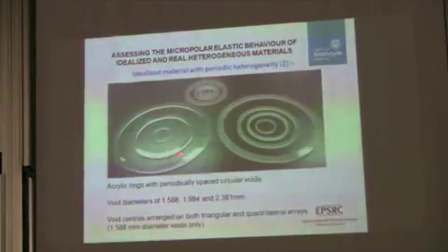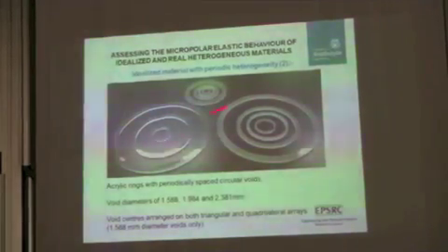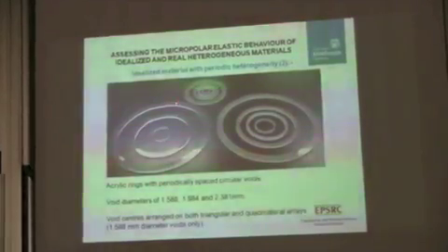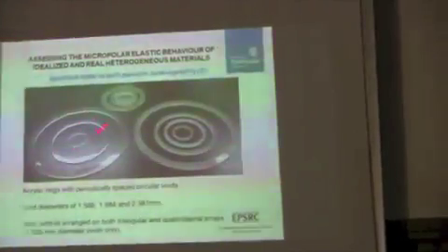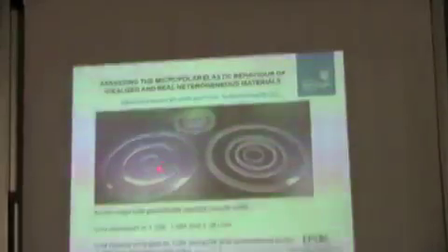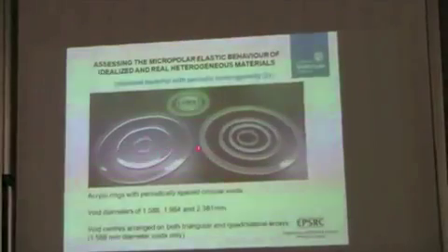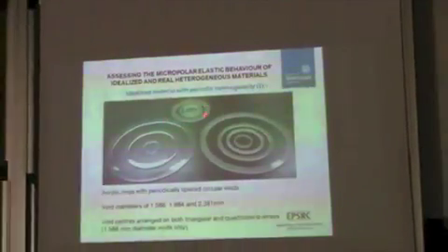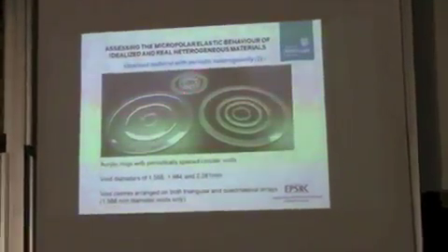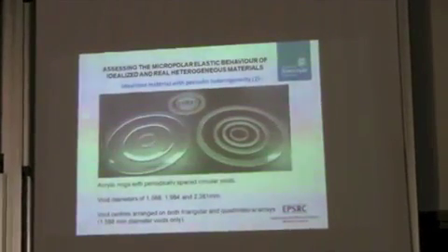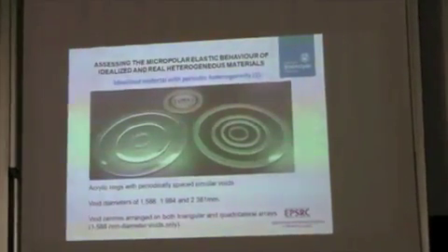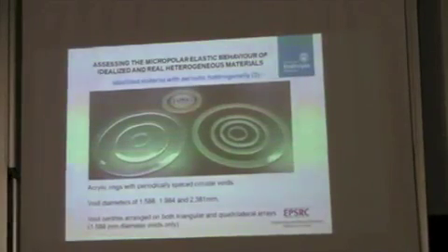Circular ring samples, again, we've got on the right here a set of slender ring samples which have these perforations machined into them. On the left here we've got a set of samples that have no perforations in them. We use this set of samples just for determining the Young's modulus of the matrix material. And then we've got this set of samples up the top here which have a lower aspect ratio. And I'll come back to the significance of those samples later in the presentation.